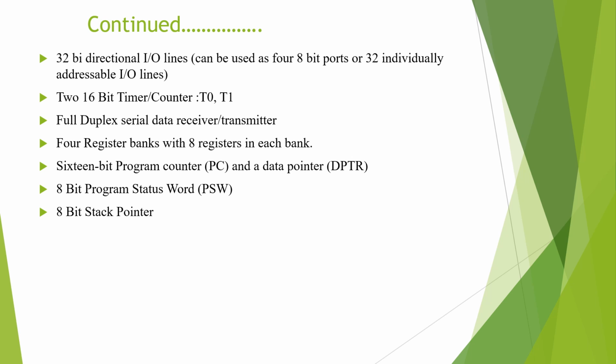In that case, when the processor transfers its job from task 1 to task 2, it will store the temporary data and the address location of the next instruction of task 1 in any register bank, so that when it comes back from task 2, it will directly fetch all the information it needs to restart task 1 from that particular register bank.